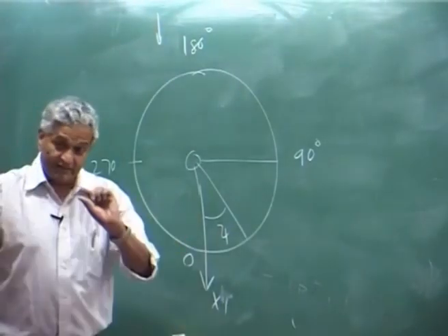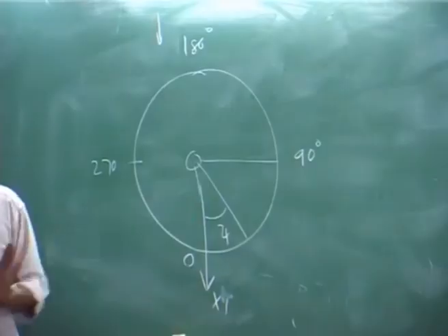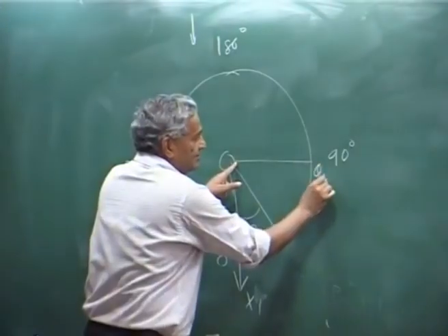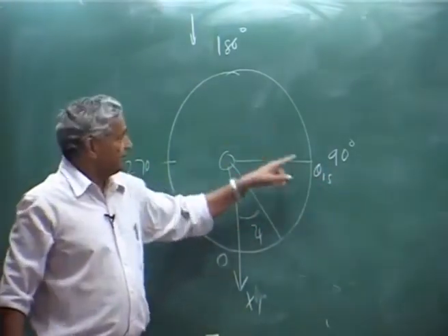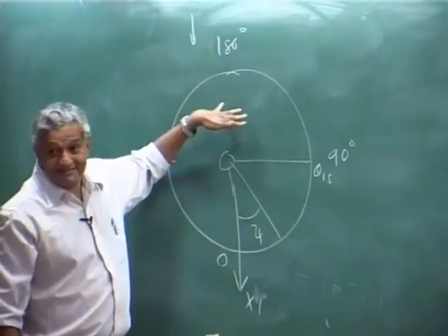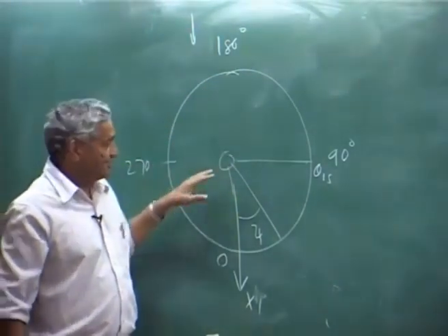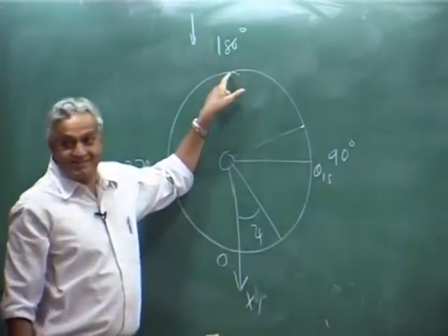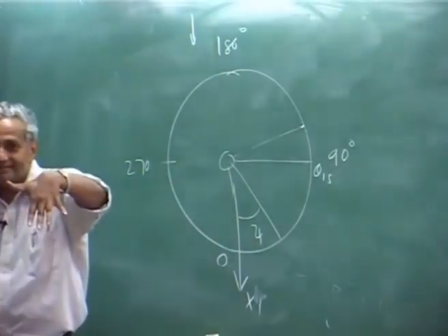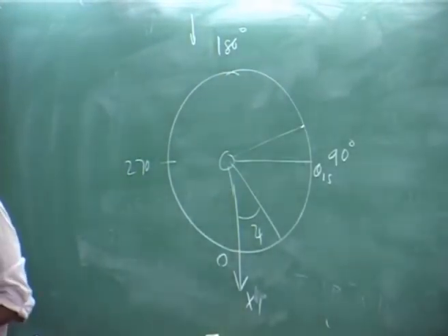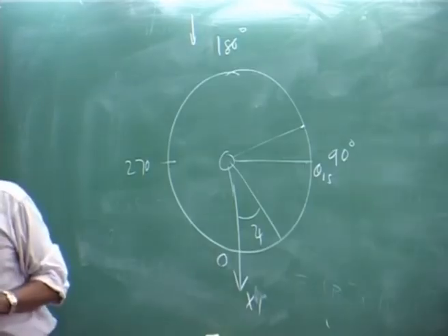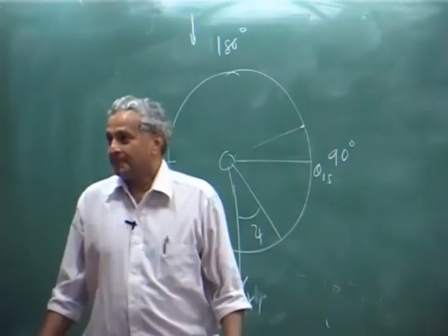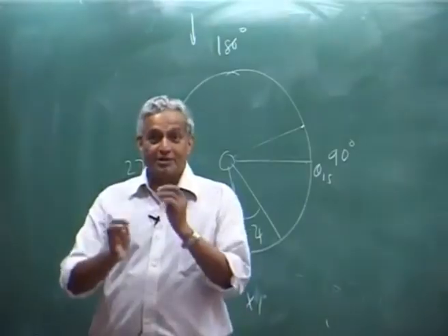Just I am saying, because forward flight also will change, we are doing just hover case, okay. If I give here theta 1 s, what it will do is, it will go until here, this will go like this. So, what normally done is, when a pilot gives, he will give an input somewhere here, so that this rotor disc tilts. So, he will go forward. So, they try to reduce the coupling. That rigging is done in the mechanical arrangement of your control rods.